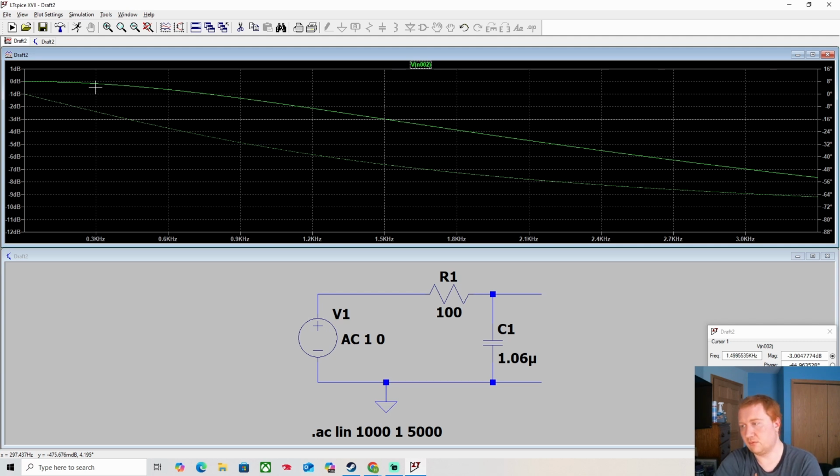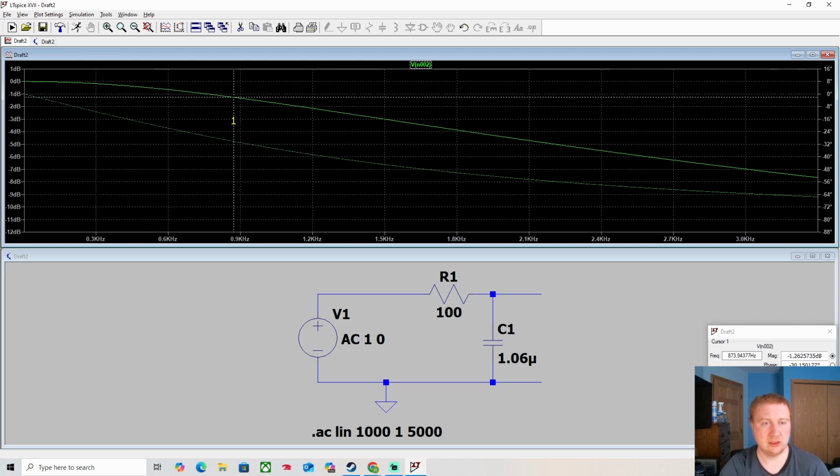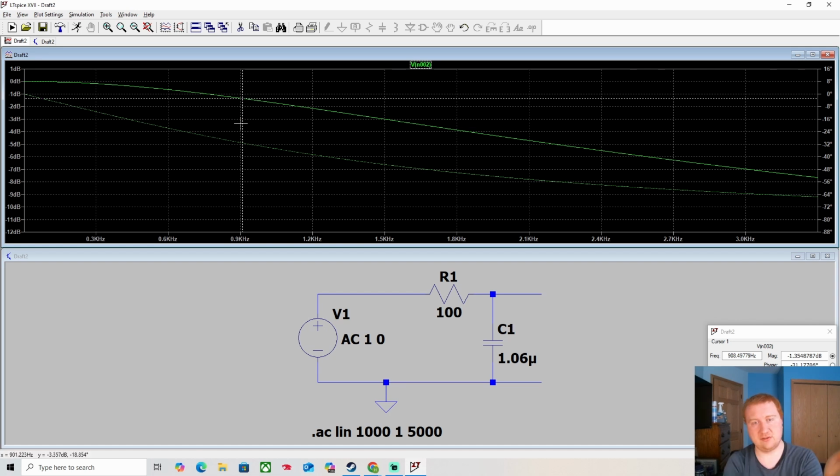So an RC filter is not ideal because we lose power here. In all actuality, with this particular combination of parts, if you consider a 1 decibel loss, I'd say about 1,000 hertz approximately. Then it starts reducing quite a lot.